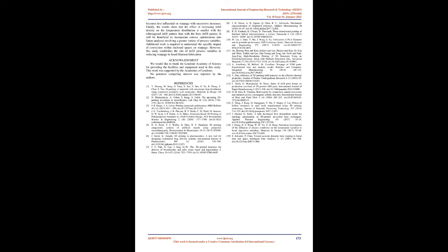Based on the results of this study, the infill process variables, infill pattern and infill density, seem to have a substantial effect on the isotropy of the temperature distributions and consequently on part warpage. Studying more variables, such as wall thickness and layer height, can widen the range of parameters used in this analysis. More process variables and measurements for each increment of these variables enables the problem of warpage to be treated as a convex optimization problem.